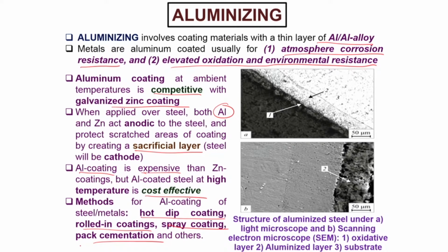So, when we coat aluminum on steel, this is how it appears in cross section. Essentially you will have a coated layer, and then an interdiffusion layer, where the first layer will be very rich in aluminum, and then aluminum concentration as a function of depth will decrease, and then this is the substrate which is unaffected. This layer thickness will depend upon the process parameters, typically the chemical potential, temperature, time, and so on.